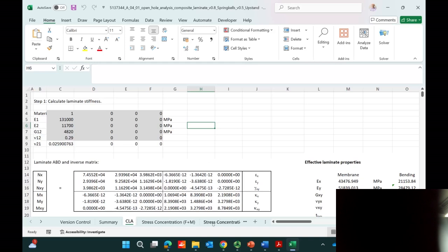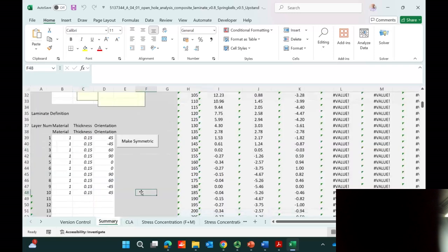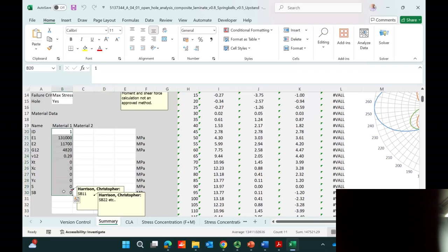So for all of this, we're assuming properties of the matrix, right? Because you don't actually put the matrix of the material. No, when you give this mechanical property, we'll see it in the next lecture probably, it is given to you. This mechanical property is the combined mechanical property of the matrix and the fiber. So the fiber itself, the modulus of elasticity is around 170, 180. When combined with the matrix, it will become 130 or 131. So this comes from the tensile testing, the actual combined matrix and fiber, not just the fiber.